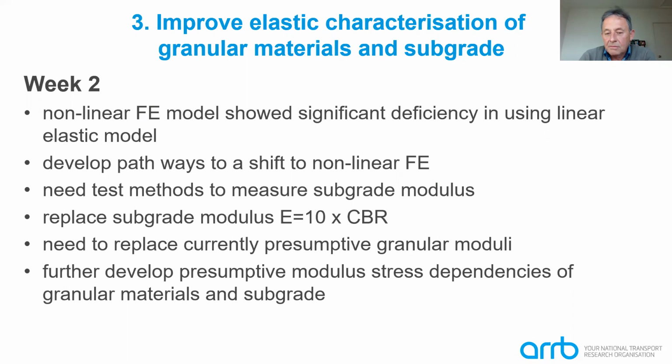We also use a lot of presumptive values for granular moduli rather than using measured values, and that is tied to the simplified linear elastic model we use. If we had a non-linear finite element model, we would be in a better position to move away from those, and to assist in that respect, we need to develop presumptive moduli stress dependencies for granular materials and subgrades.